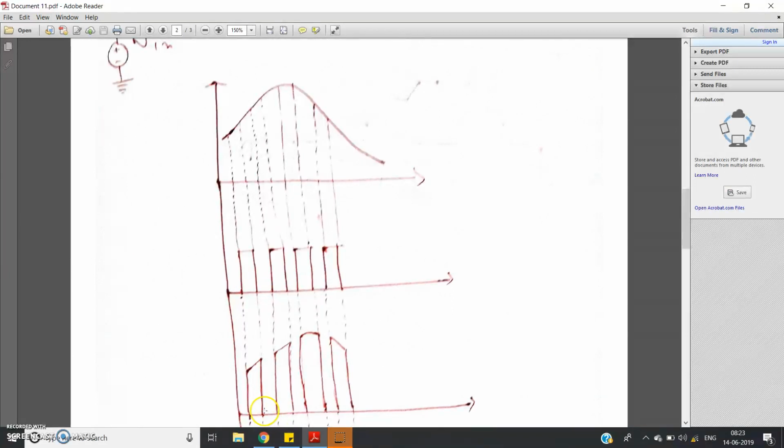Okay, so what will happen? So basically here you will get 0 volt. Then again see, here we are applying again a square pulse, so gate voltage is equal to VDD, so MOSFET is turned on. So what will happen? Corresponding to this particular square waveform, the input voltage is this. Okay, see here this particular input voltage is passed here. Okay, like this you will get this kind of waveform in the output side. So this is called sampling, right? In your analog communication course, you already studied pulse amplitude modulation or natural sampling, flat sampling in detail.